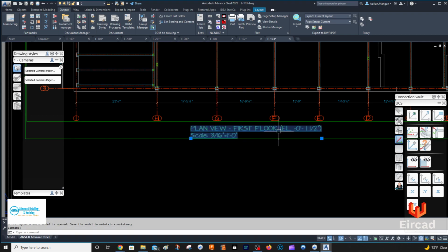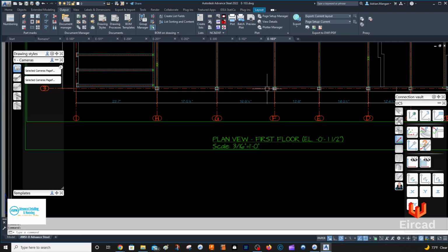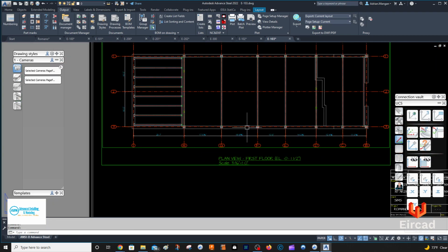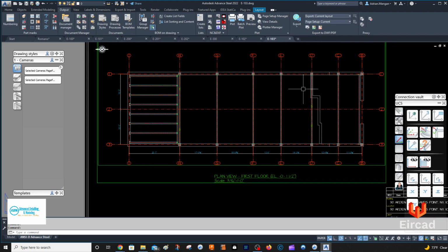Now these walls that I've created here are solids. I stated at the start that I like to create them in solids, and then I'll go back when I know they're in the right place, and then I'll create them as concrete objects. So I need to do that to have these drawings correct. So I'm not worrying about that right now. And this will come in with a hatch then. Or you could just double click on it.